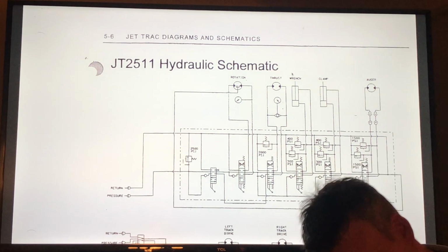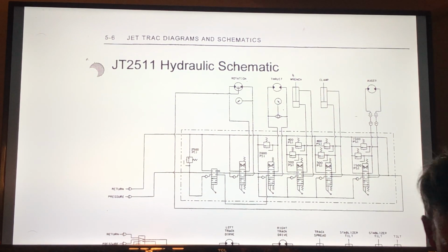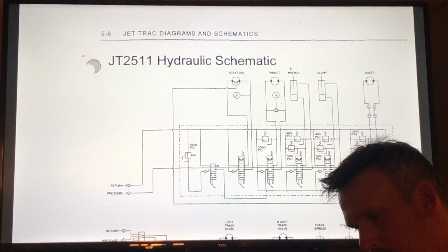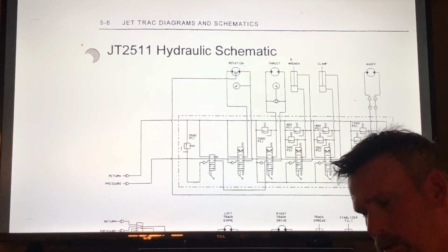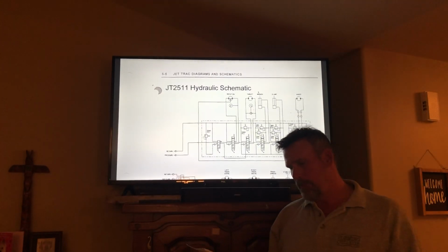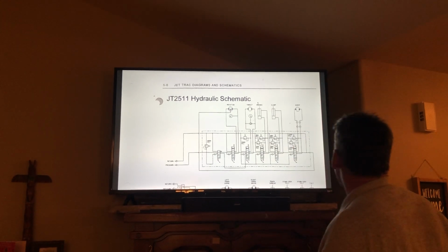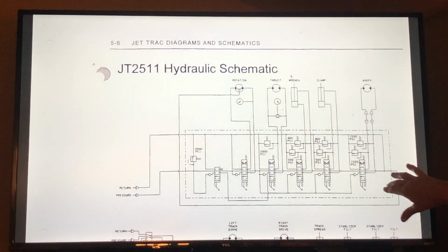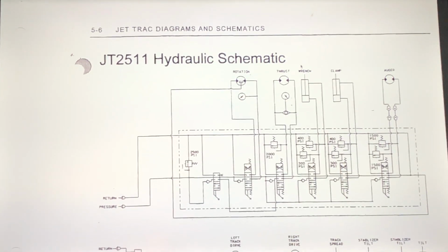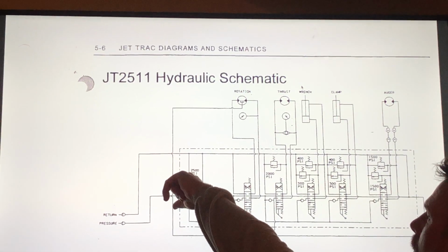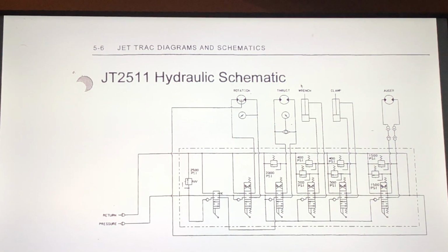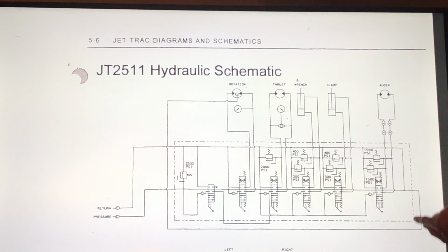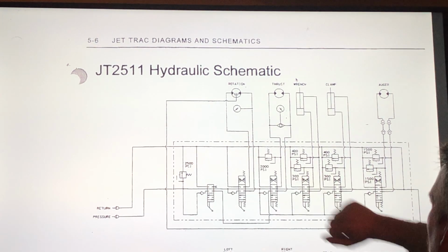All right, so question 3. When high pressure is generated in the auger circuit, does oil escape through the main relief or the circuit relief? All right, so here's our auger circuit. Once again, we go back to where the relief valves are. So here's the main relief in the valve, and it's set at 2500 psi. This is our component enclosure, which shows that this is a DCV.